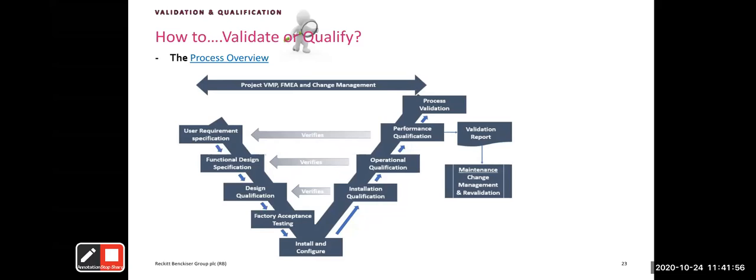Now, the same thing happens with manufacturing equipment. You do your user requirement specifications, you send it out to factories, and they send you their different designs, and you narrow down to one particular factory. You go to that factory, you do your site acceptance test, confirm that what they actually claim they are doing can be delivered to you on site. Then you come back and say, okay, fine, place the order, and they place the order. The equipment arrives at your factory, and right from the point where you're opening the case for this equipment, you're looking at every element, the packing list of what came with that equipment. I want to confirm that they meet what you asked for in your user requirement specification.